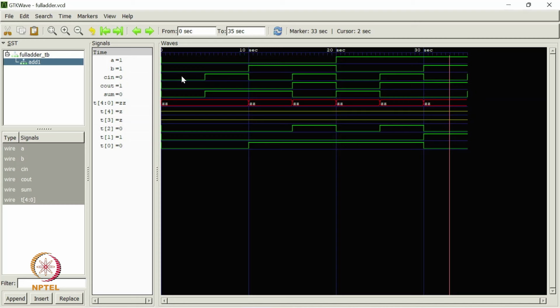For example, the first stage 0 0 0, that vector we again add in the test bench after all the 8 lines. So, there will be a 9th line which is a repetition of the first one, then we will see all the values comfortably. So, here now we have these 7 lines and the 8th is kind of not shown here because the simulation ended right after application of the signal. So, we can look at these waveforms and cross verify with our truth table whether these waveforms are correct or not. Wherever we click, that will show the input output values here in this signals window.